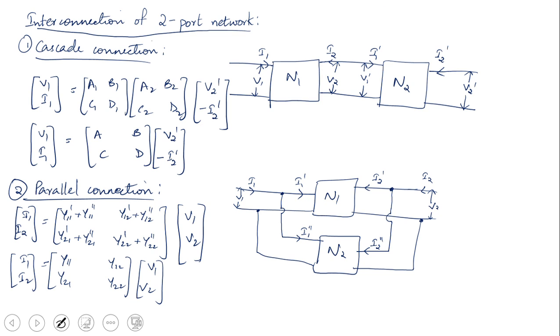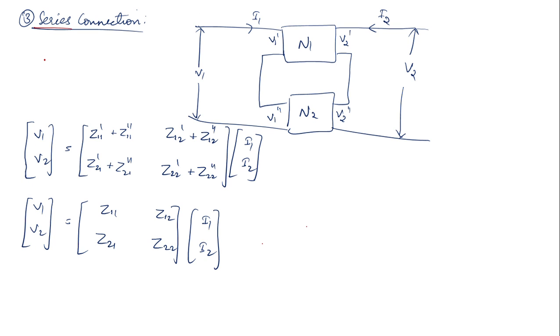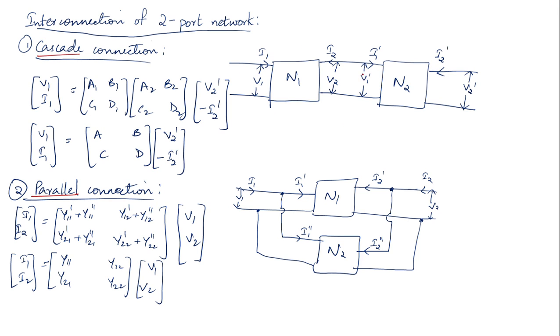Today we are just going to deal with some of the important equations that you need to know in the fifth module. And we are going to first deal with some of the equations related to the interconnection of two-port networks. Now over here we have three types of connection. You have the cascade connection, you have the parallel connection, and you have the series connection. Okay, so if you see any of the networks in any of these particular formats, then you can find out the parameters by using simple relationships instead of carrying out the whole analysis in one step itself. Okay, so it is mostly easier if you can identify the networks, whether they are cascade, parallel, or series.